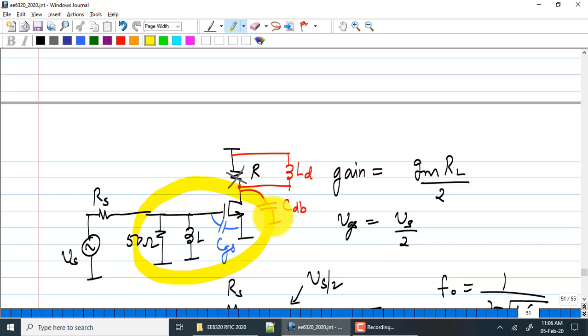Okay. Now, just remember that if you go to very, very small feature length processes, the physical gate resistance of the device itself could be significant. Okay, so your input, which you thought was capacitive, could also have a real part, which means you will need to change this 50 ohms, RS prime. You will need to change it appropriately.